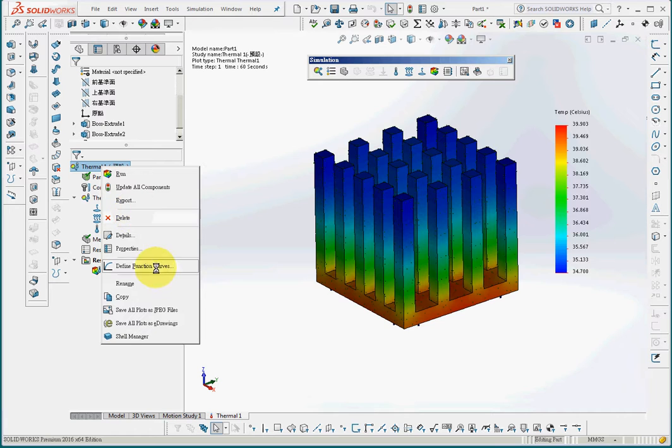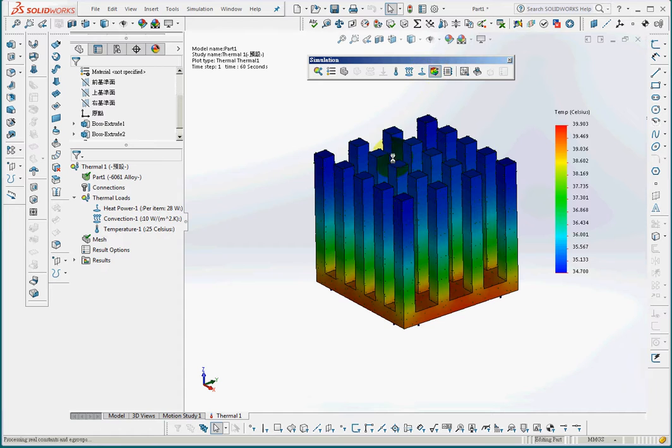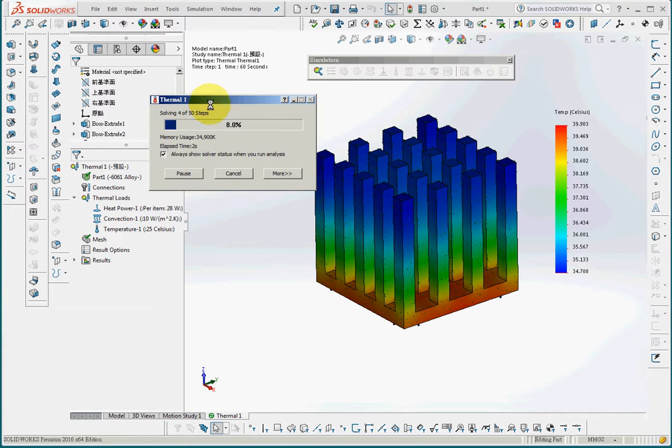So now I'll change the properties and change the time to, for example, 2,000 seconds, or even 3,000 seconds. I'll make sure the system reaches a steady state that I can compare with the former example. In the last example, we know that the temperature here at time of infinity reached 152 degrees Celsius.